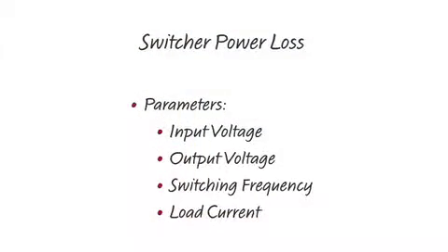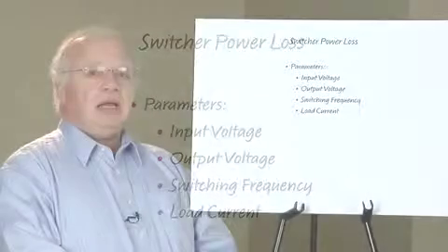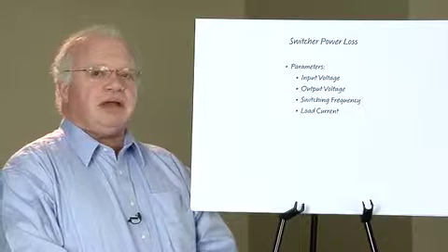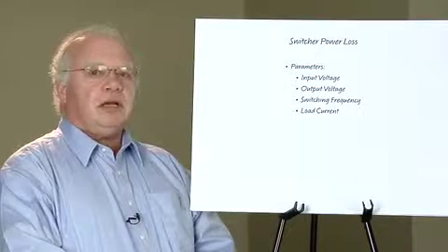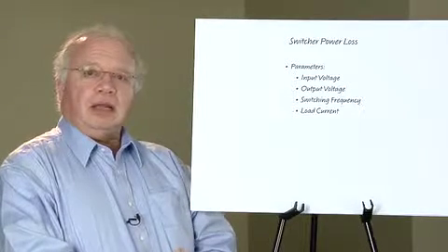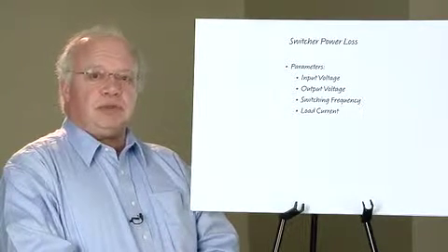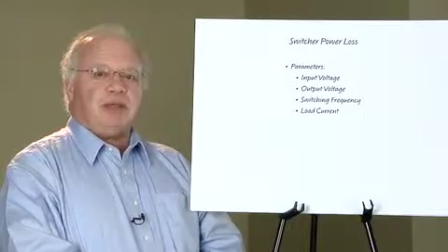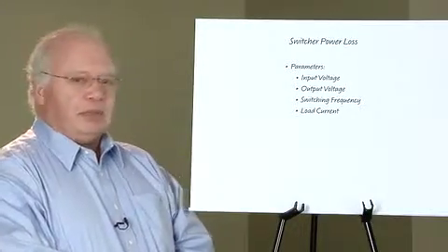The next thing that we want to look at is output voltage. How does that affect our power loss? Output voltage doesn't affect the power loss very much, but it affects the efficiency a lot, and it can give misleading results when comparing different switching regulators, and we'll talk about that in a minute.